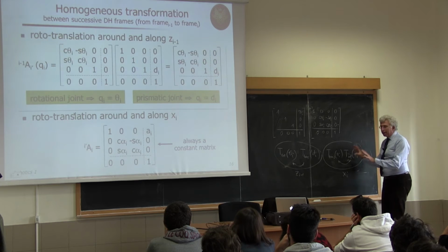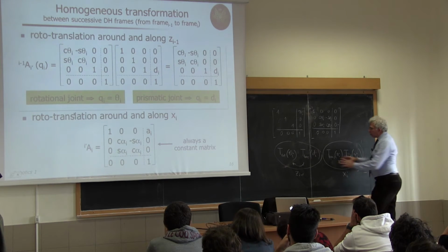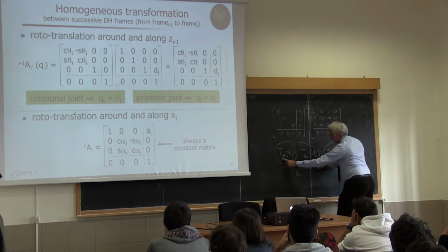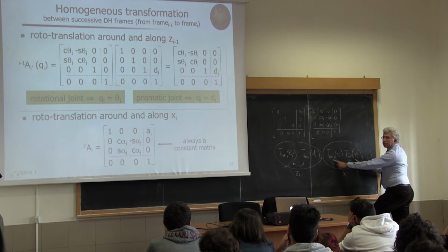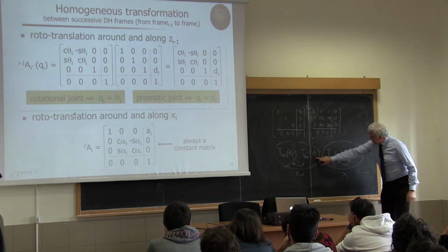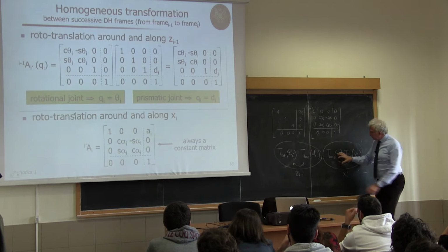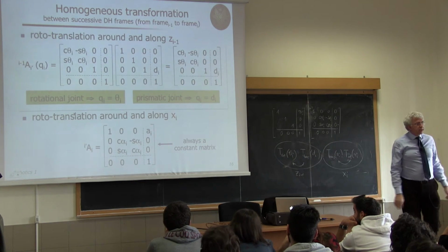So I can do multiple things, just by reasoning about this product of homogeneous transformation matrices. I can write translation rotation or rotation translation like this. I can write translation rotation or rotation translation, but I will keep it like this. Now I see here there are two contiguous things, a translation and a translation. Can I interchange them? Can I place this here and this here, even if they are along different axes?